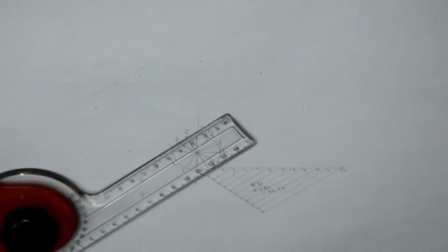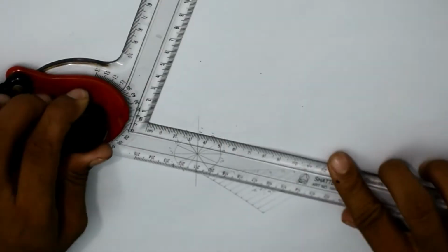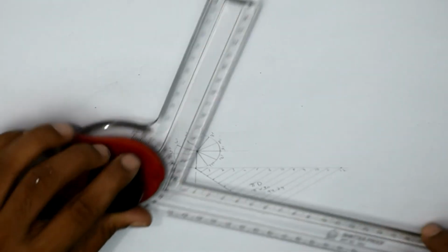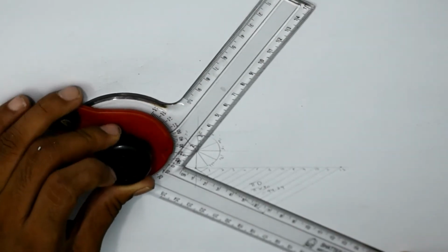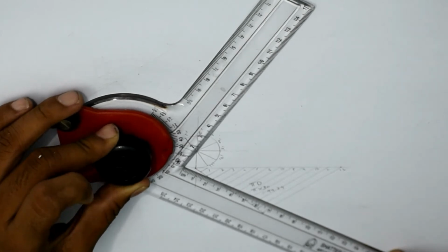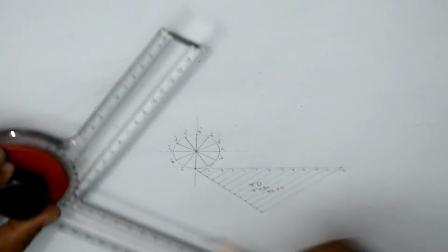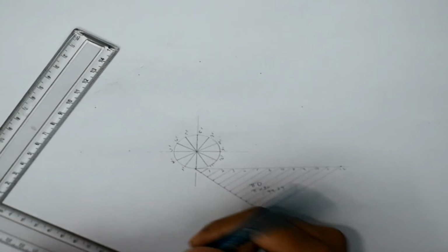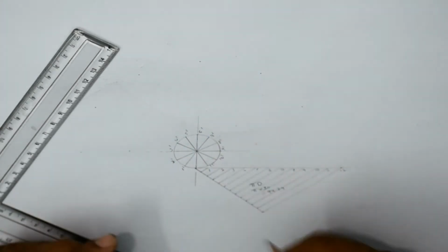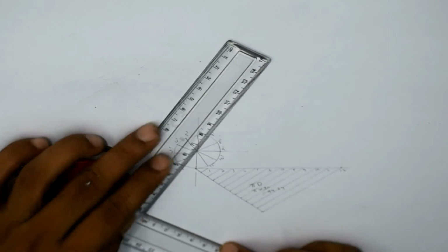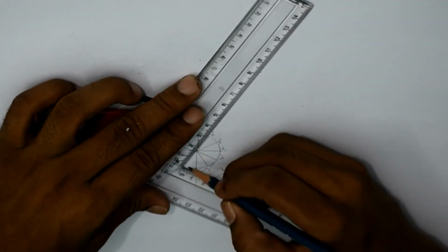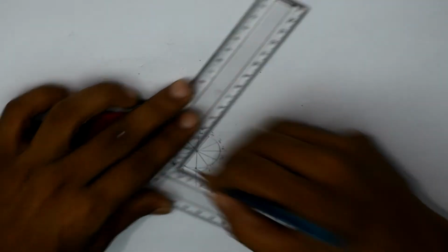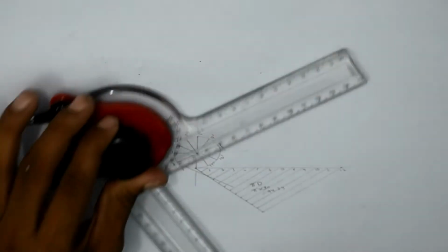Tangent. So what is a tangent? Tangent will touch the circle only once. Like this, if I draw a line here, this will be a tangent. But we have to take divisions from the point. Observe here very carefully, I am aligning this line of the drafter with the first line. You see that this is the first line, 1 dash. So I am making this drafter align with this line, and at this point I am drawing one line. See this one line, and I will follow the same procedure.